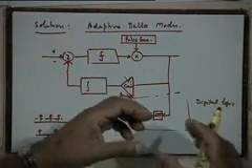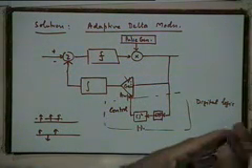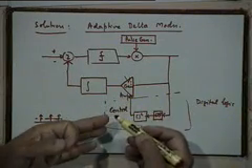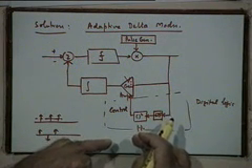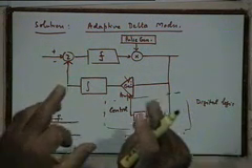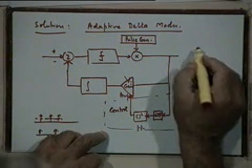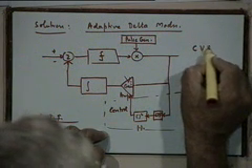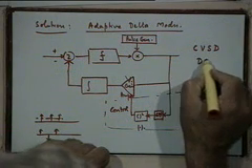For example, you can have a digital logic which can track whether a few successive pulses are of the same sign or different sign, and produce a control signal based on that. So this can be replaced by a suitable digital logic as well. If you do things like this, this particular kind of adaptive delta modulator is called a continuously variable slope detector delta modulator, CVSD delta modulator.